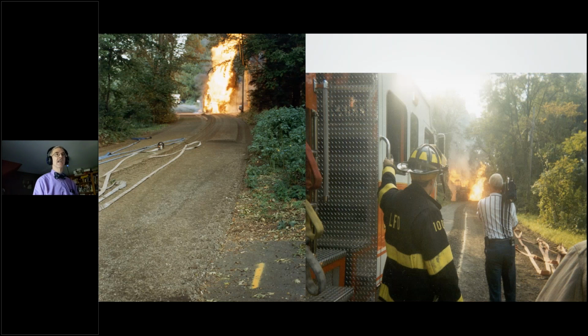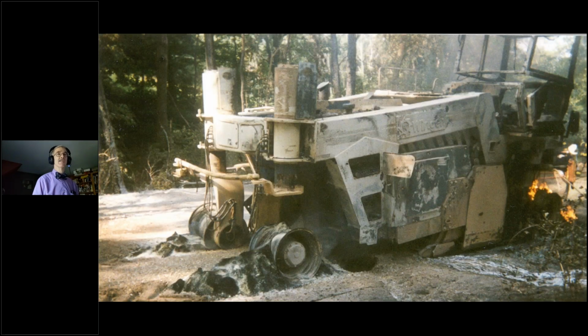Please be safe. You can see they actually did call in this particular case. There's the yellow mark. What's the yellow mark mean? Yeah, gas. Absolutely. What you see is a gas line on fire. They were doing reclamation work, full depth reclamation, but they were only going down about 9 inches. So technically, they weren't down a foot. But it's nice to know, if they'd properly marked it, where the line was. But instead, the line was in the road 9 inches down, and they hit it with the reclamation machine.